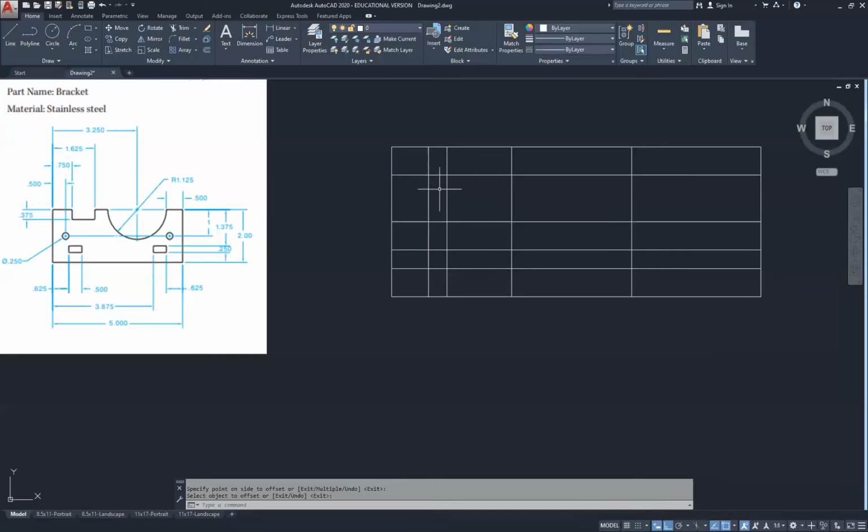So the first offset, this line here, and this offset right here at the 1 inch, I'm going to change those two line types to center line so we can keep track of them. I can also go ahead and put a delinear dimension in from here to there to verify that's our 0.5. And then this dimension from here to there is our 1.